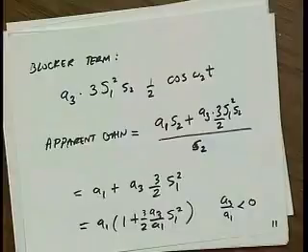Now, true, there is intermodulation distortion that we already took care of last lecture, right? You get intermodulation products. What we're seeing here is that even if you could filter out those intermodulation products, you're still going to experience less gain in your system. So this is not an intermodulation term. This is the term at omega 2, the desired frequency. So the gain of our system has apparently dropped because of this jammer. Well, I guess my question is that basically we're susceptible to everything that's outside of our band. That's true. And that's why it's so difficult to build radios, because you don't have a very well-defined spectrum.